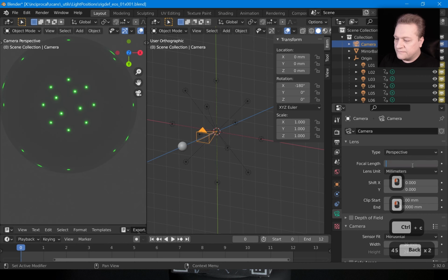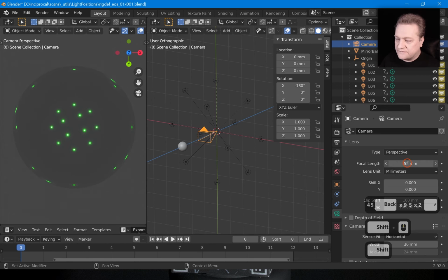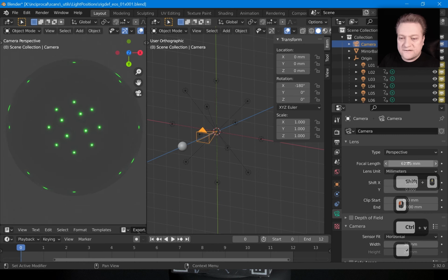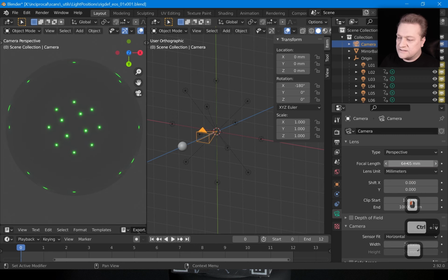If we go from 55, that was 55, if you look at that image on the left, to 61, there is quite a bit of change, even though it's not a big difference, but there is a difference. So if we want to be more accurate, it's better to do that estimation step. If in your case it doesn't change too much between these values, you could probably go directly to light calibration, skipping all that estimation step with photogrammetry.